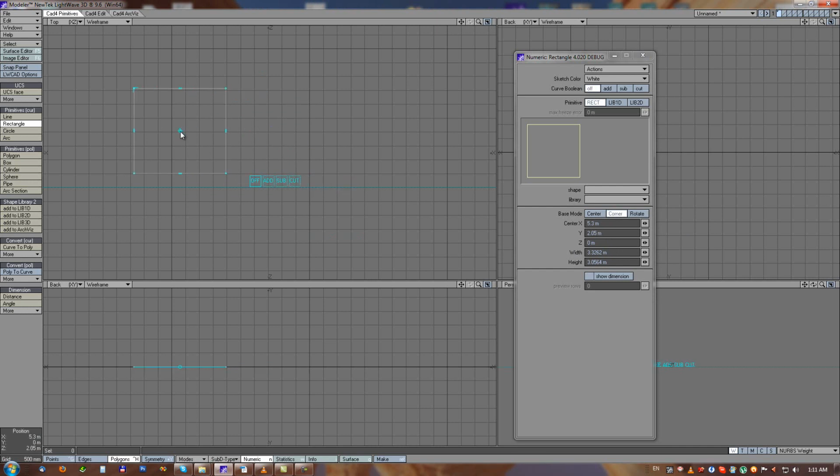So if I want to place this rectangle from this point and place it precisely to left and down, I just change width in the numeric panel, and the object is scaled from the active pivot into the opposite side. This is maybe a little hidden feature, but very useful.